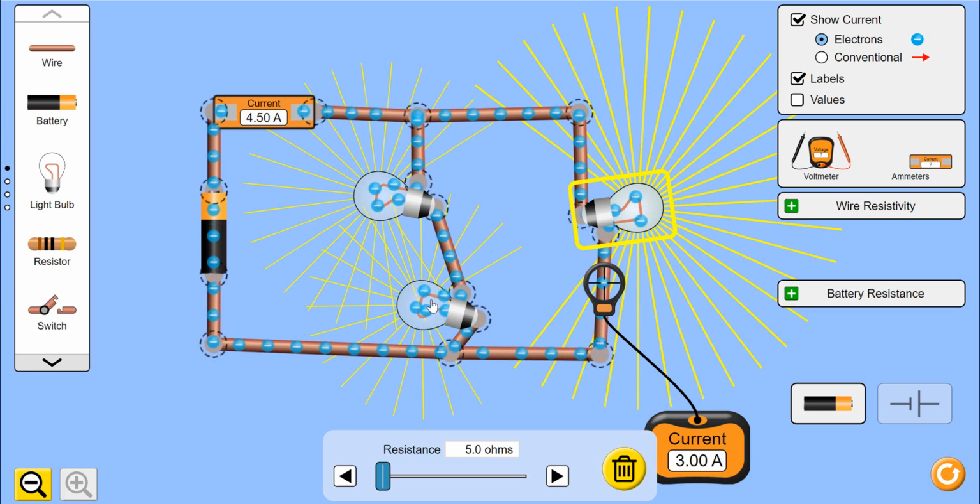We have the yellow streaks here showing you how bright these light bulbs are. We had calculated the power on this one here was the dimmest bulb. This one here converts more joules per second. This one here converts the most, because if you imagine for the parallel path, I have all 15 volts available to brighten this bulb here. If you track that there, again, we have 3 amps worth of current, no problem.